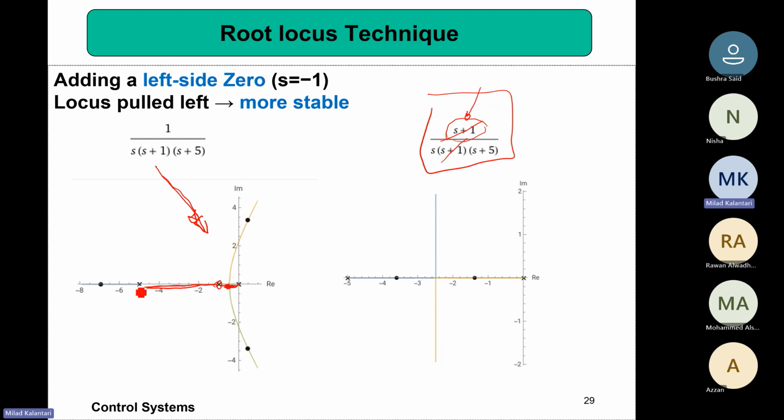And then this region afterward cannot be root locus, right? Because now you have an even number of roots and poles. Basically what you have is only this region of the root on the real axis, right?